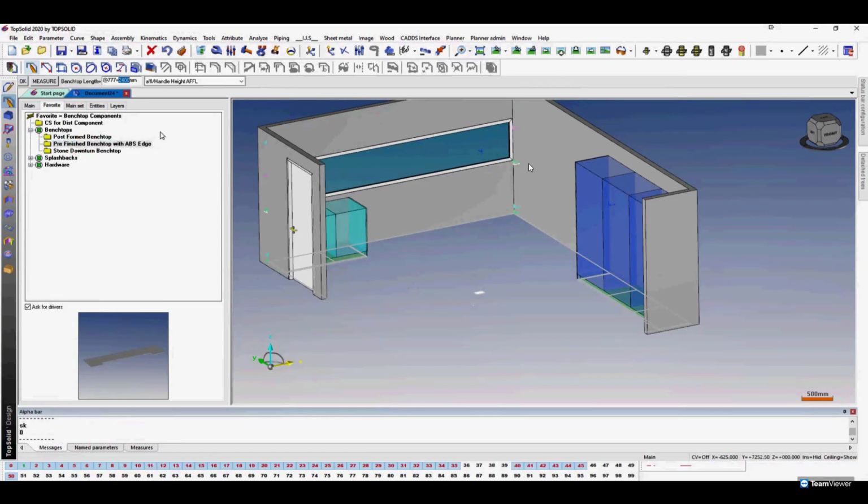Continuing that, I'm going to bring in a benchtop, depth. The length of the benchtop isn't important at this stage because I'm going to tell it the length in the inclusion. So when I go distribution, I say between that coordinate system and this coordinate system, that's the length I've given it. As you can see, the benchtop is there. It's got a mason's miter already on it, and it's got the toggle bolts on it.